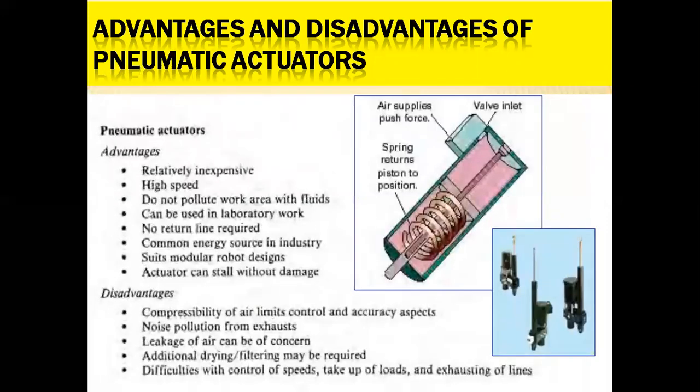We will have a glance at the pneumatic advantages and disadvantages. It is relatively inexpensive, and quick actions can be performed. It can be used in laboratory work also for very speedy operation. No return line is required, and it suits modern robotic designs, only to particular limits and extents.